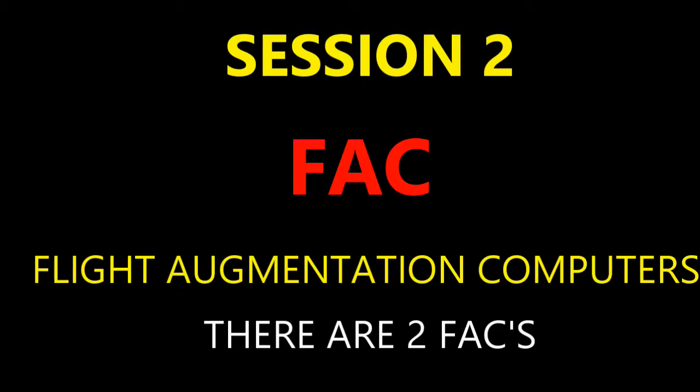Remember I mentioned alpha floor, and I said I might as well mention it now, right? So I did earlier with alpha floor. I've been mentioning the aircraft energy, and then I defined wind shear for you so that we can talk about these things now. When we talk about the flight envelope, we want to make sure that we are keeping within certain parameters, that we have certain thresholds that we don't want to go past, and we will make sure we stay within those thresholds. And so this has a lot to do with the performance of the aircraft, right?